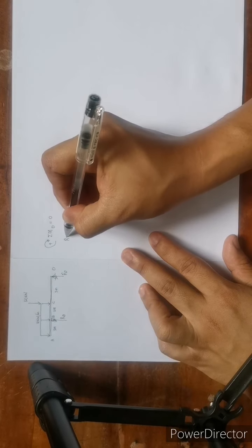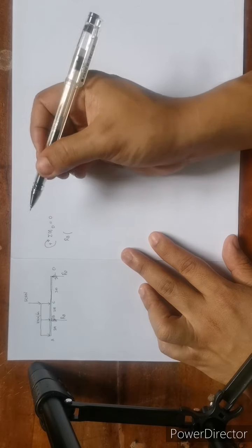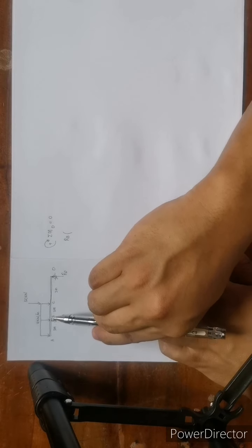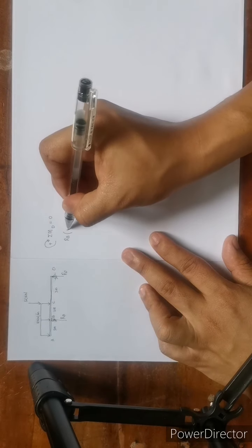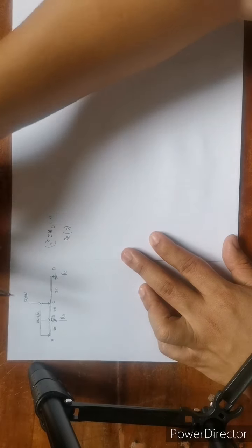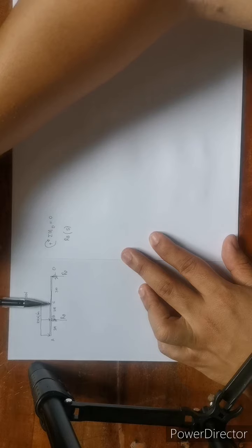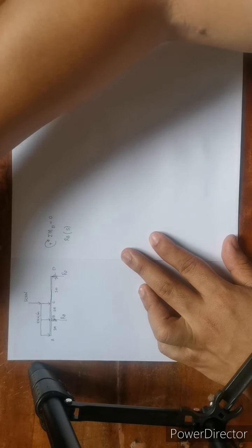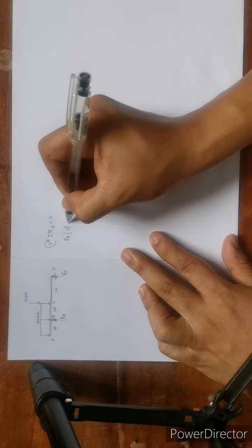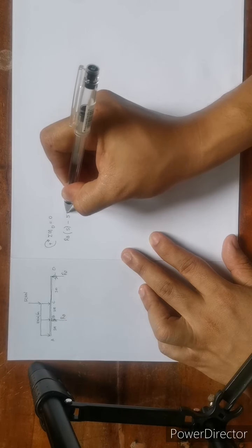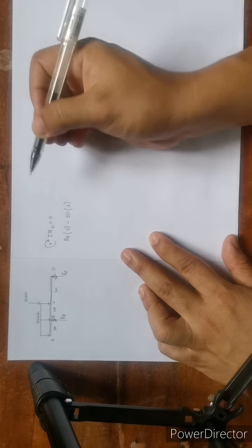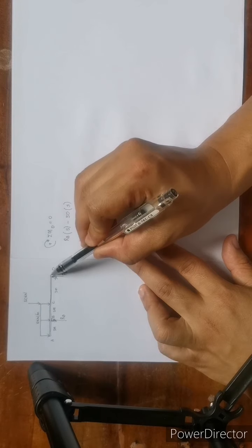So, that is reaction at point B multiplied by the perpendicular distance. Ano yung perpendicular distance niya? Papunta kay point D. Ito yung perpendicular distance. That is a total of 5 meters. And then, we have also a 50 kN force here. Papunta kay point D, ang kanyang direction is counterclockwise. So, that is a negative moment. So, that is force 50 times perpendicular distance of 3 meters. Ito yung perpendicular distance niya.